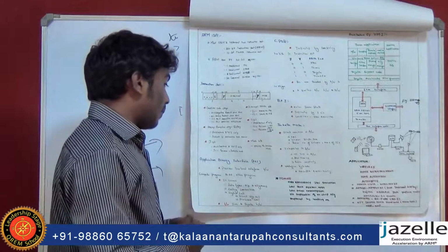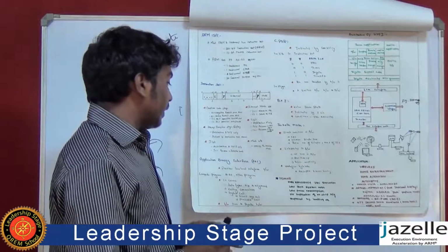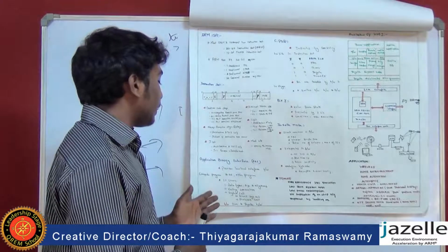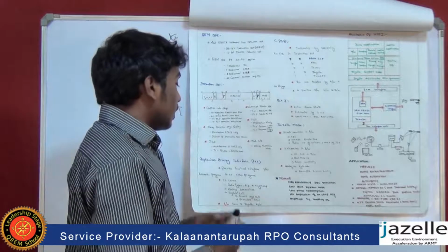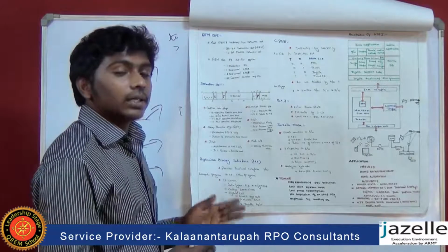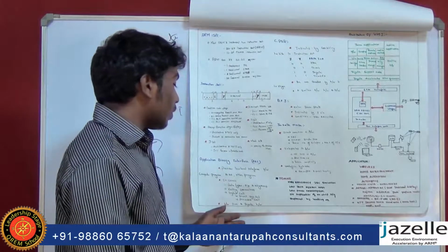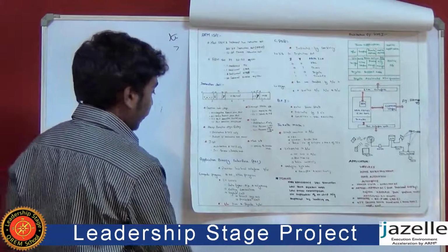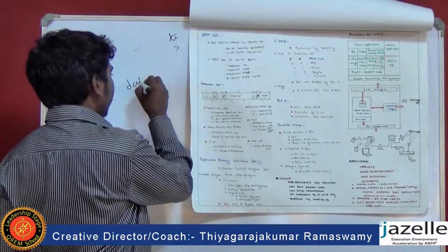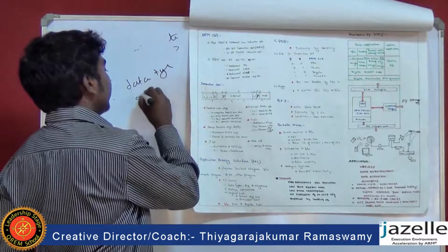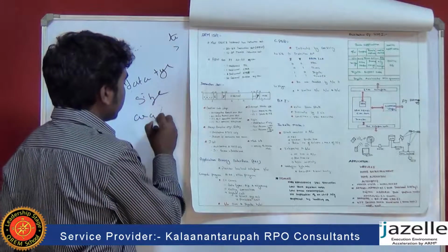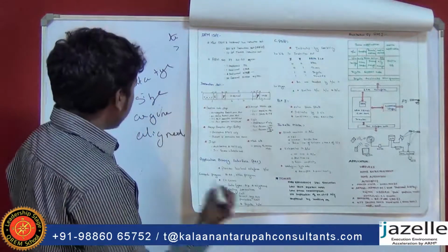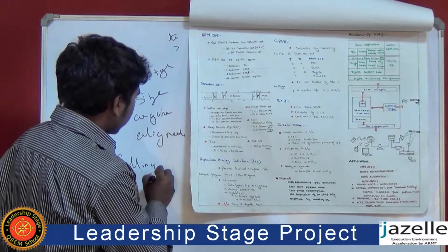And the next one is application binary interface. The application binary interface is a low-level interface that is used as an interface between the OS, computer programs and other programs. In Jazelle, it is used as an interface between the JVM and the Jazelle hardware. It covers things like data type, size of the data, argument alignments, and it is also used for calling convention.